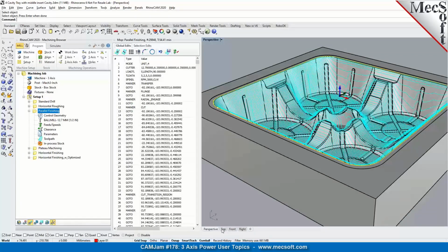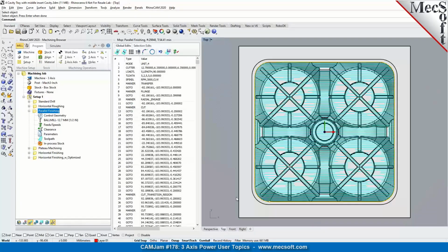Now let's say you had a part that requires a very long job run. It could probably run over several hours or has to run overnight, and you may want to stop it and then go back the next day and continue from where you left off. So rather than having to go back and reprogram and regenerate the toolpath for those sections, you can use the toolpath editor and go into the selection edits tab, and you can select a section of the toolpath and delete it.